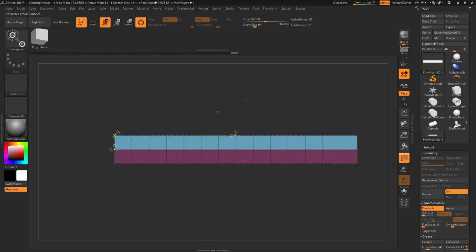That is why we added those edge loops there before we came through and started bending our mesh. Another thing we can do with this bend arc deformer is apply masking while it's active to only have the bend affect just a part of my model. I only want this part of the blade to have that bend, and I want this part to remain straight. So I'm going to hold down Control on my keyboard. This is going to give me the mask pen.